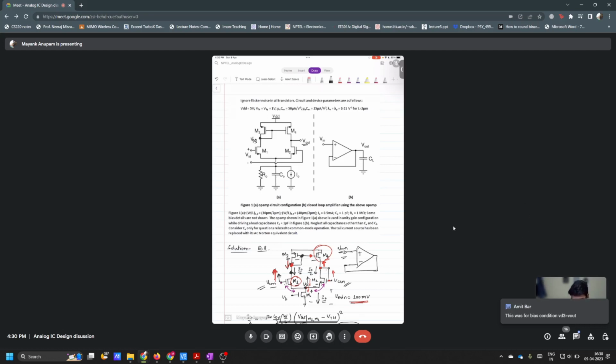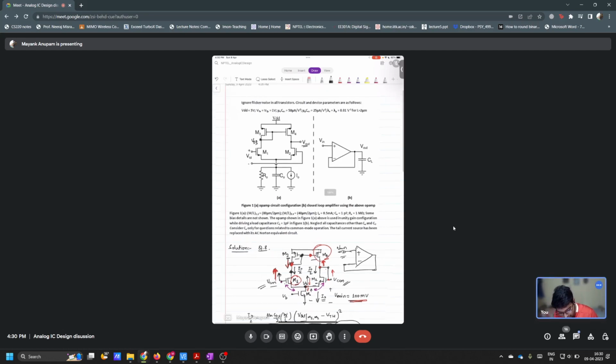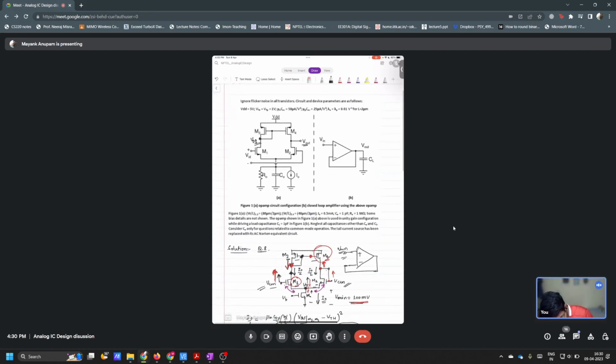So this is basically when you set the biases. At that time these two voltages have to be equal; they can be nothing but equal. But if GDS were equal to zero, you cannot definitely say what the relation between these two will be. That is the problem. But for all practical cases, GDS is not equal to zero. So these two will have to be equal to each other, and there is no other possibility for the bias condition. Mind it, only when these two voltages are exactly the same.